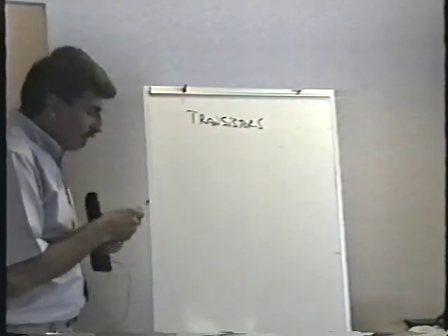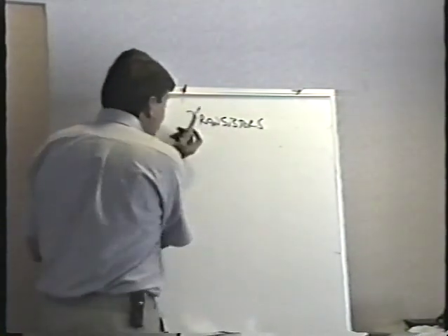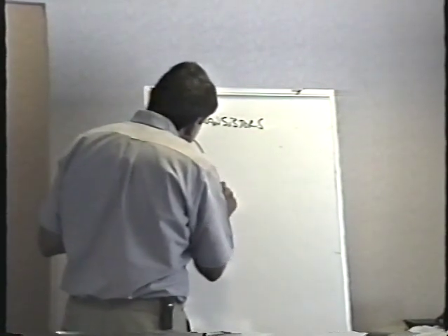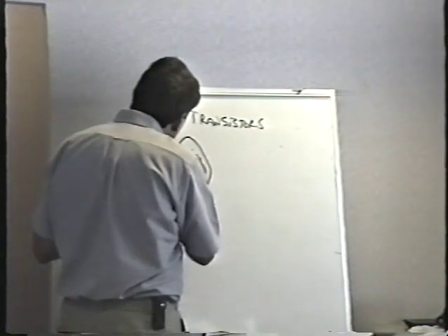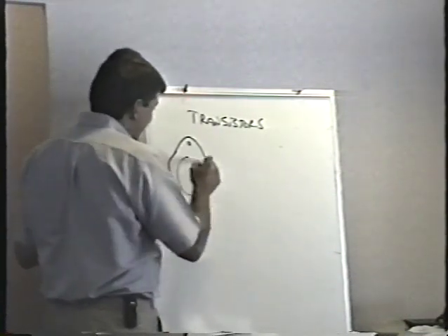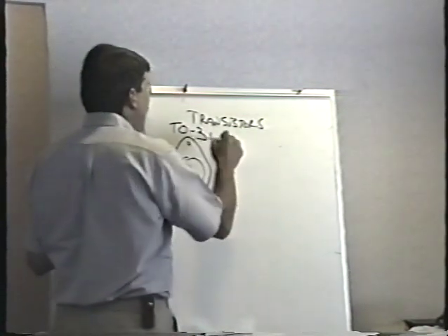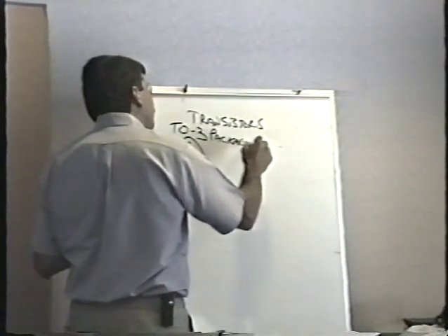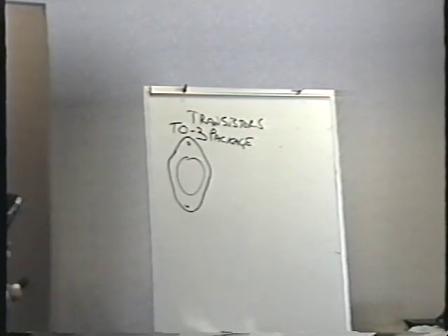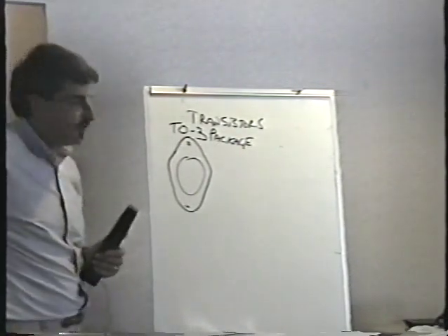Transistors come in a wide variety of different shapes and sizes, different packages. You have 3 of those different packages, and each package has a different designation. The giant transistor that I gave you that looks kind of like that, not exactly, this kind of guy right here, is known as a transistor in the TO3 package. That's transistor outline number 3, is really where that came from, the TO3 package. Commonly referred to as a power transistor, but it's really just a transistor in the TO3 package.